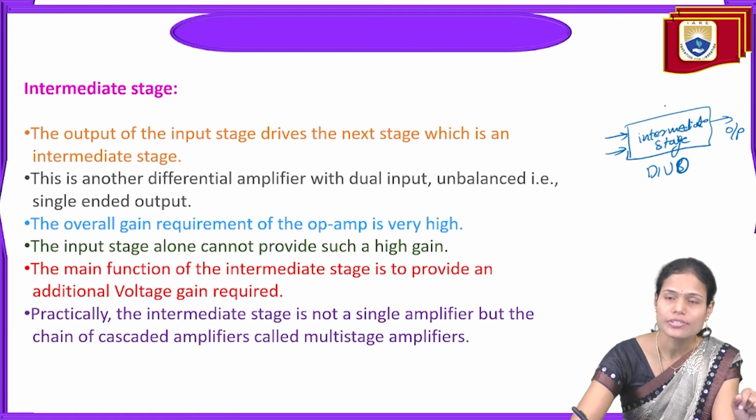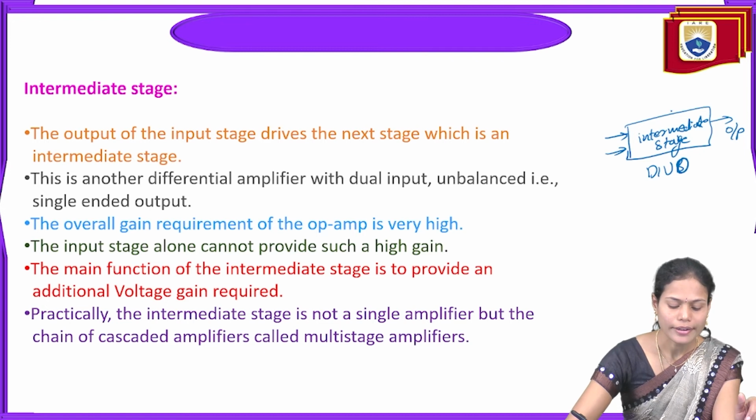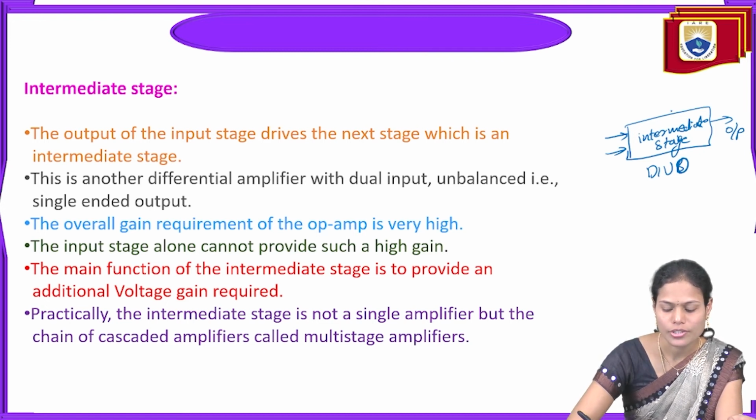The basic function of these intermediate stages is to provide the very high voltage gain, or the voltage gain required for the applications. And practically this intermediate stage is not a single amplifier; it is a cascade connection of multiple differential amplifiers.